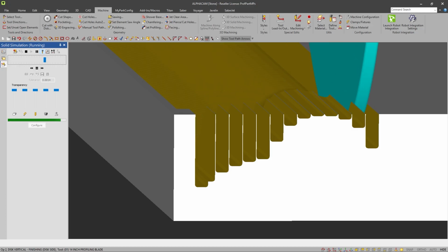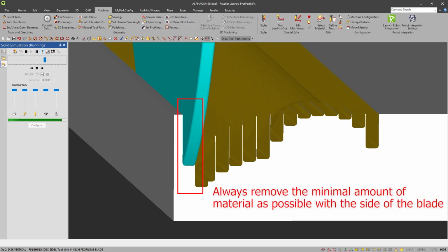Then blade width and blade spacing make up the roughing pass back to the other end, which doesn't necessarily go all the way to the edge like the finish pass will. The finish pass will go from one end of the profile to the other, completely finishing it.